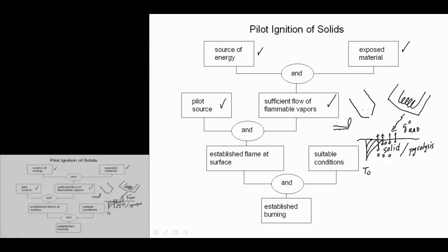The flammable vapors, so these are actually just fuel vapors. I should have talked about that. So these fuel vapors are hot because we've heated this relative to, say, the environmental temperature. Let's say the environment was at T0. And so you get a buoyant plume of these vapors, but what that buoyant plume is also doing is it's entraining air from the outside of the region that's being locally heated, and that is in fact what causes us to have this flammable mixture.